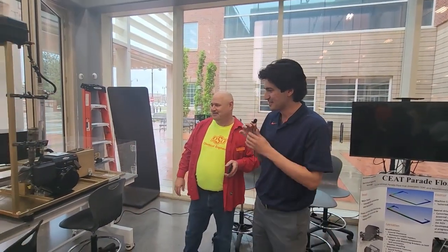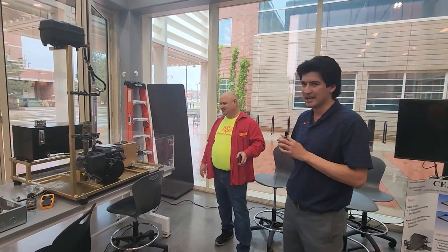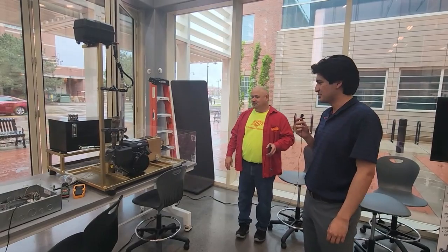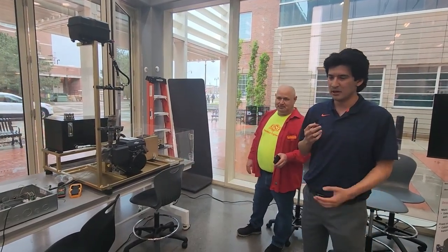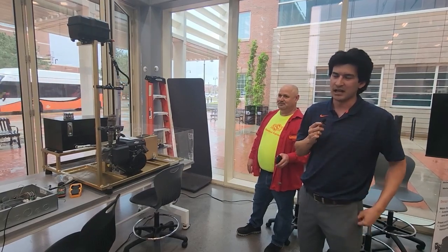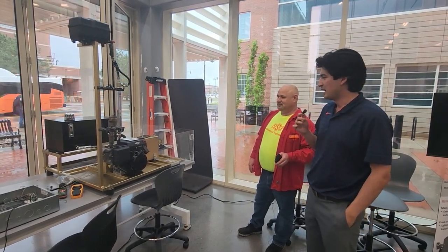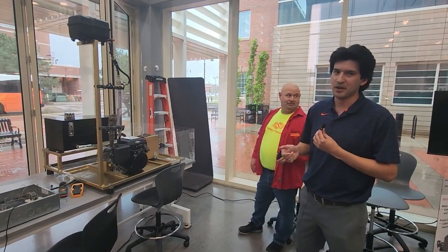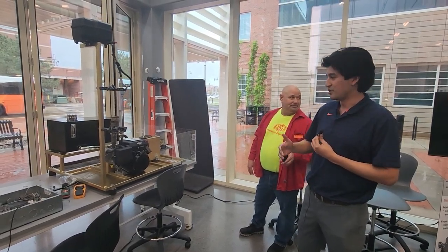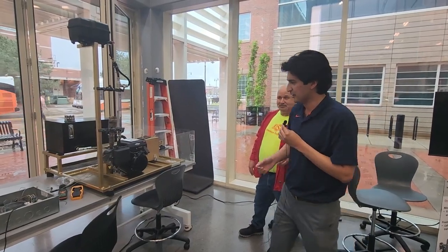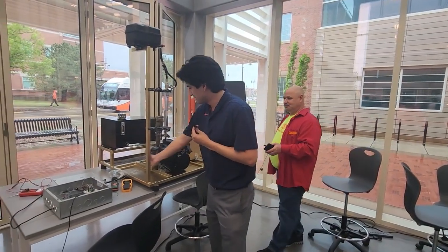Okay, yeah, so this is our project. We had to make a dynamometer for this engine here. The way we did it is we went with a hydraulic dynamometer. Essentially we're using the engine to turn a hydraulic gear pump. And using the control valve on the system, we can restrict the flow and create back pressure, which will in turn add a load to the engine. And we can measure the load with these sensors we got over here.